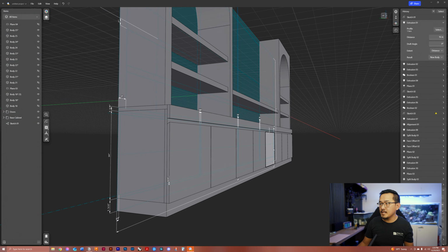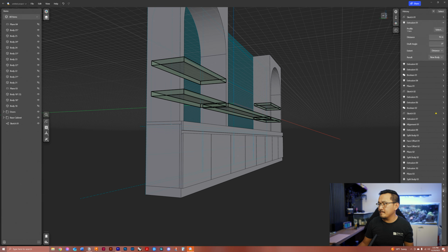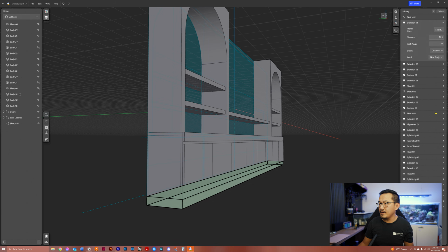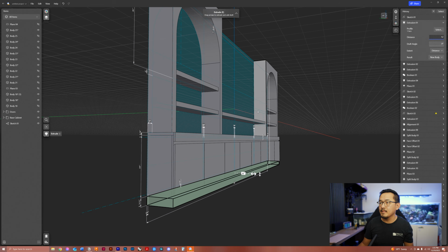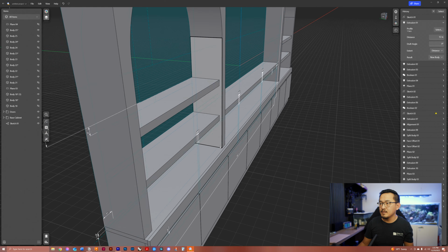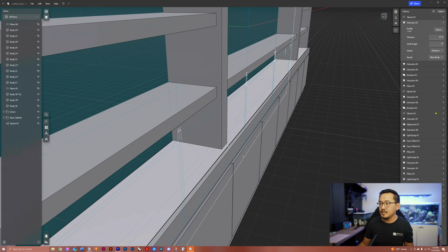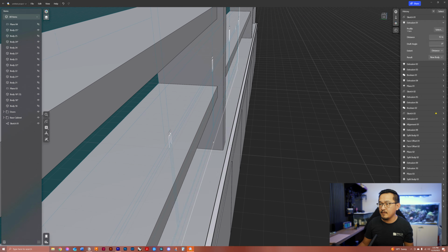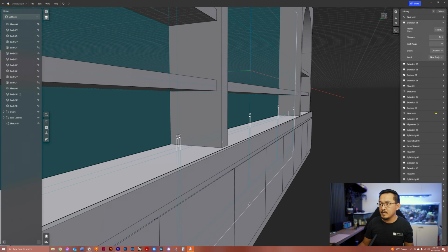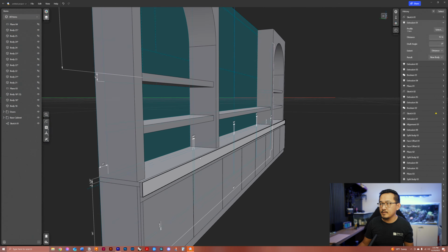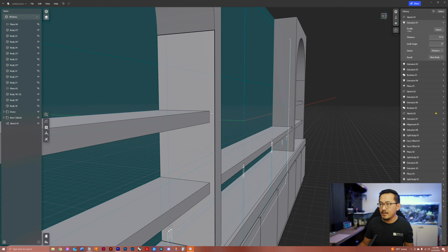If we take a look at our base structure, the toe kick, if I move this to 12, everything moves accordingly. You can see the distance is maintained between the countertop front and the arch, and I still have my 1 inch there.